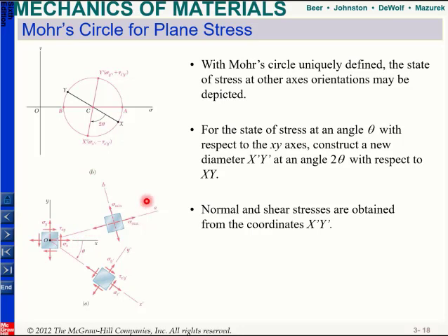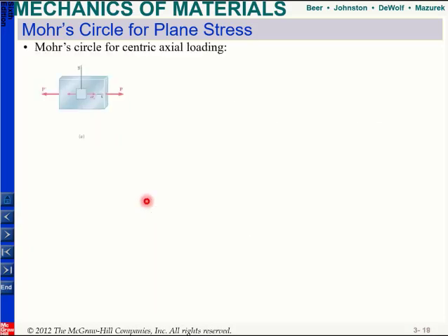And what we will do next is look at some cases and try to construct our Mohr circle. The basic one is tension experiments. You have a sample and you apply some load. I'm looking at this configuration, so my X is along the load applied and my Y is perpendicular to that. If you calculate your stresses, you only have normal stress, which is equal to P over A, and your shear and other normal stress are equal to 0.